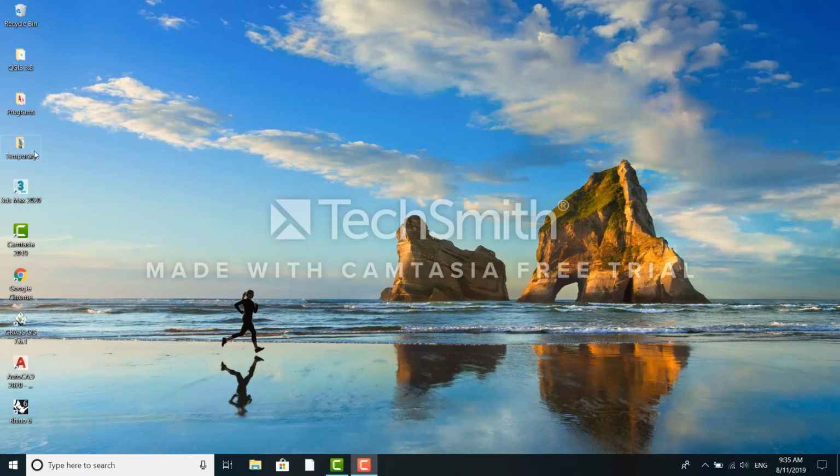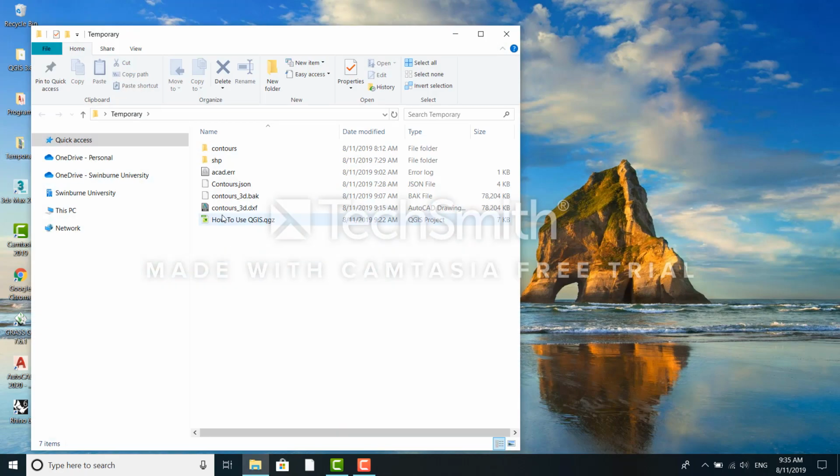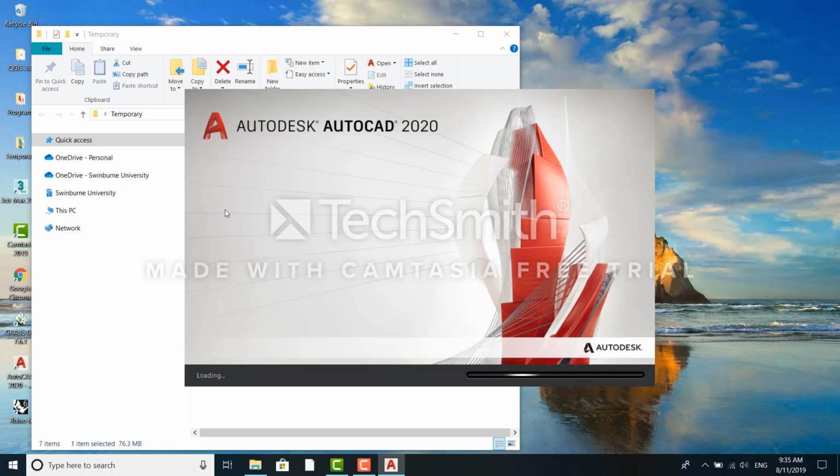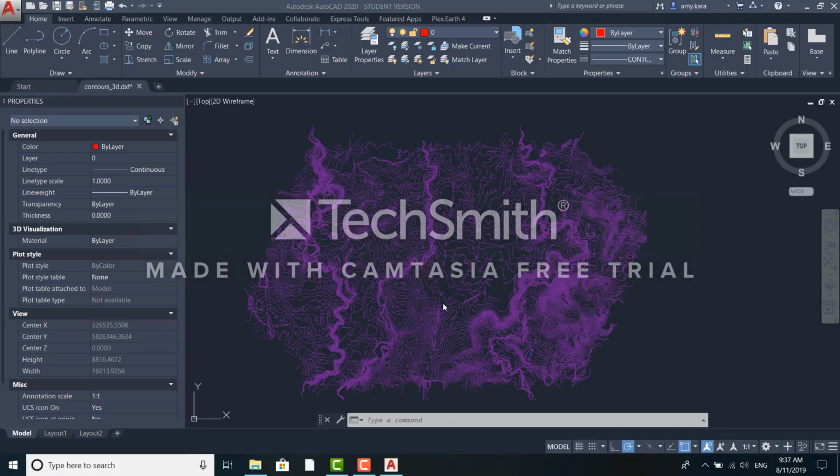Anyway, let's get started. The first thing we're going to do is to open the DXF in AutoCAD in order to clean up the file a bit. An important thing to note here is that 3ds Max prefers working with a site that is a clean, basic geometry shape. So today we are going to create a rectangle that includes most of the contours we've generated.